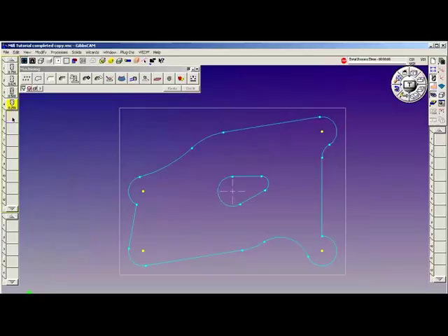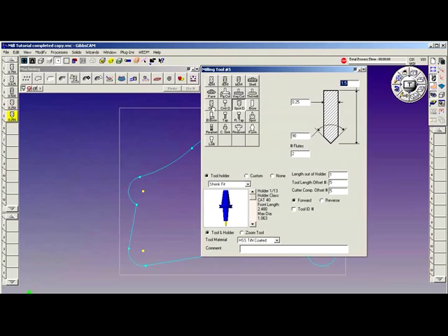We'll close this dialog. Tool number 5 is going to be a drill, for a 1/4-20 hole. The tap drill size is a number 7, which equates to a 0.201 diameter drill. That's the only change necessary. Select the drill, type in the diameter, the overall length, everything else is consistent with the previous input.